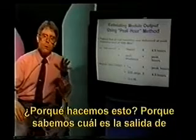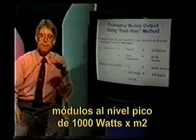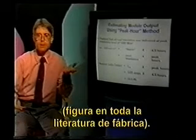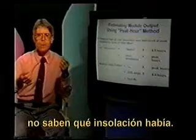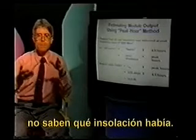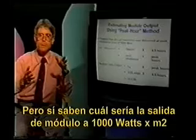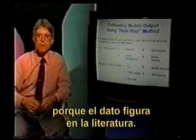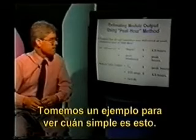Because we know module output at peak level, at 1,000 watts per square meter. It's in all manufacturers' literature. You don't know module output at 9:30 in the morning. You don't know what that insolation was. But you do know what module output would be at 1,000 watts per square meter. That comes from the manufacturer's literature. Let's look at an example, and you'll see how simple this is.